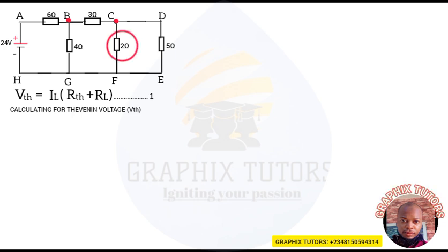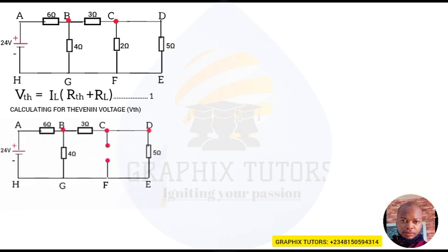So when you remove it, you will open circuit that part to show that you already removed the resistor that is there. And that will be nothing other than just a terminal. So I'll call that my terminal VTH, which is my Thevenin voltage. Are we together? Now, since we've done that, we want to get Thevenin voltage. How are we going to get that? Now listen carefully. At node C, there will be a split, meaning that the current that will be flowing through the 5 ohm resistor will not be the same current that will be flowing through the 2 ohm resistor.